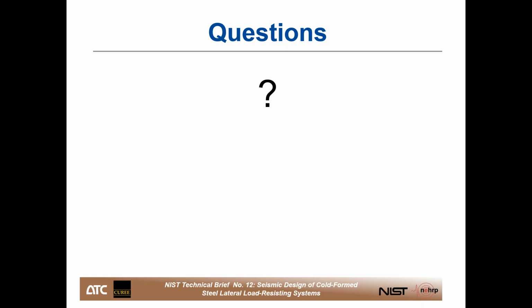First one up, for strapping in a CFS seismic force resisting system, do you recommend that the strapping be pre-tensioned? Yes. That was part of what I was just talking about in the QA/QC discussion. And I've seen a variety of ways to do it, some very complex and some very simple. But at the end of the day, you do want them to be slightly pre-tensioned.